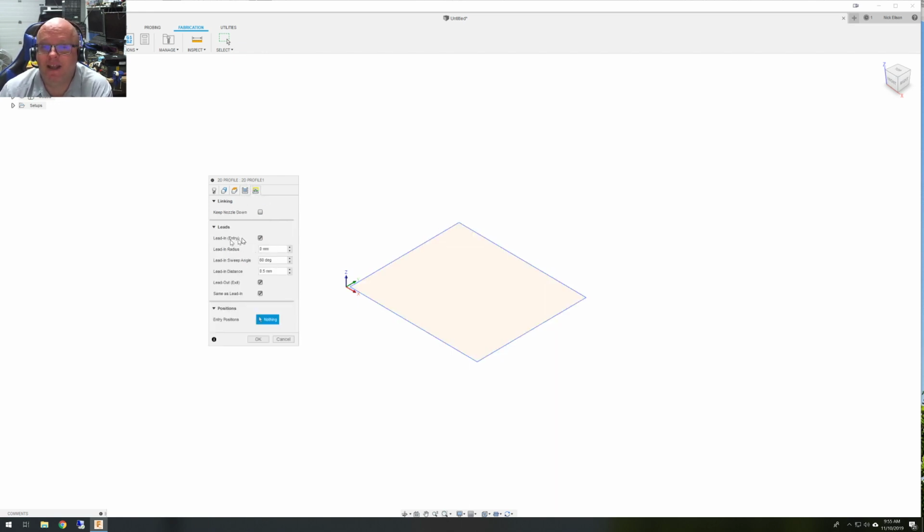And then when it comes to lead-in entry, you have these little, almost like a little flight pattern of an airplane. You kind of zip in and then start cutting, and then when you're done, you kind of zip out, and it does the laser on and off motions during those lead-in and lead-outs. So by the time it reaches the edge of your work, the laser's already ramped up to power. And I find that creates odd little cuts. I mean, if you do it right, they're actually kind of nice, and then you're never going to have underburn or overburn. But you'll have little tick marks where you can see the laser starting and stopping on your